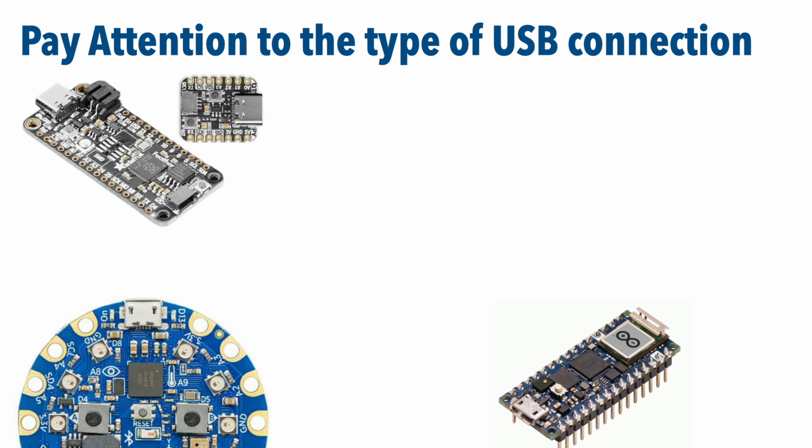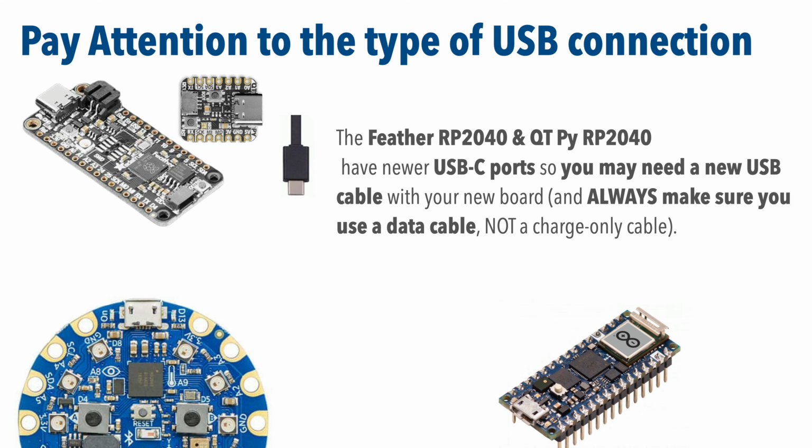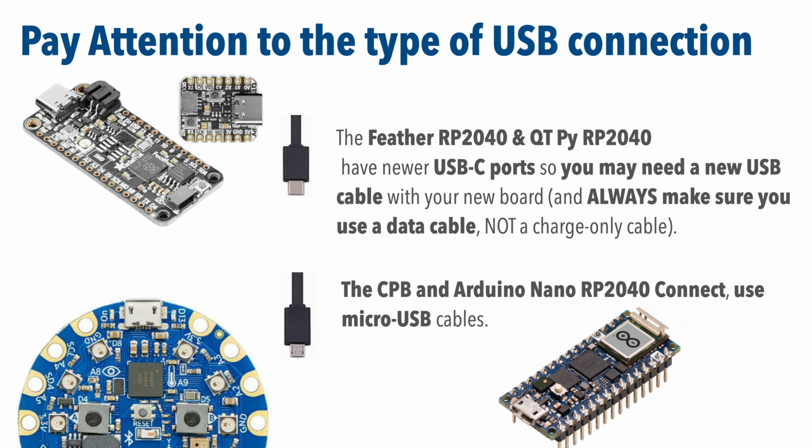check the type of USB port that the board uses. So the Feather RP2040 and QT Py RP2040 use the newer USB-C style ports, so you might need a new cable with these boards. The CPB and the Arduino Nano RP2040 Connect use older micro USB style ports. Also, always make sure that you're using a data cable and not a charge-only cable. If you use a charge-only cable, your device won't show up on your computer.